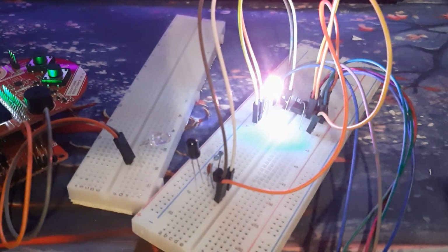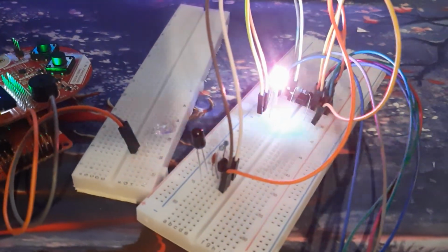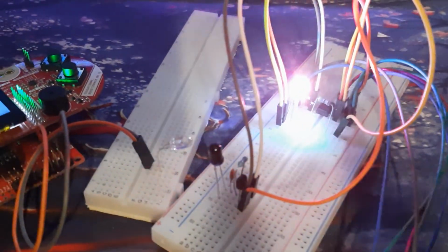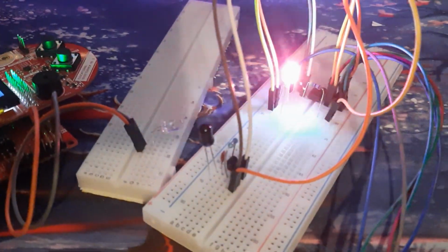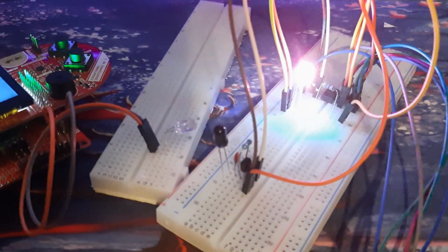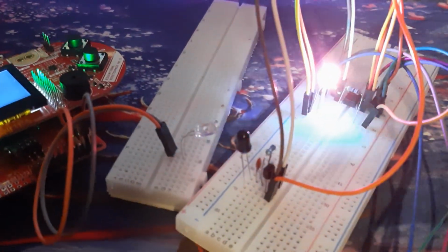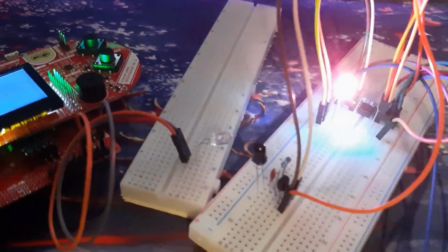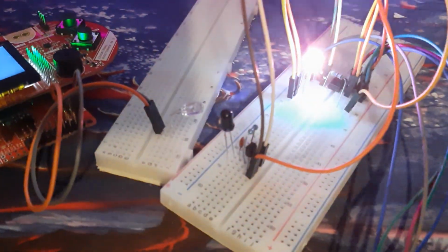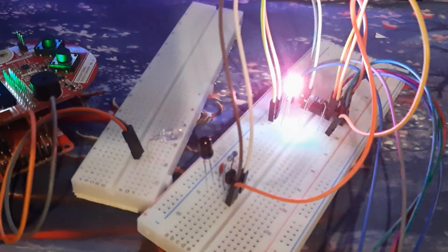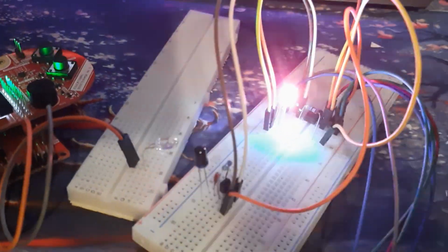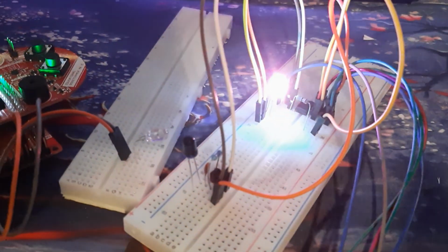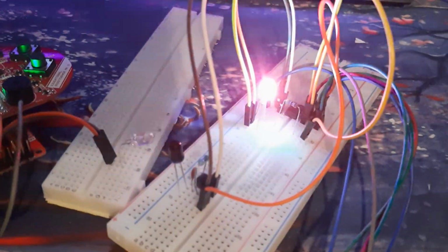So what I did is estimate the signal using a counter, which counts if this pin is pulled down on the ATtiny, and this initial signal gives me the length of each single bit transmission.